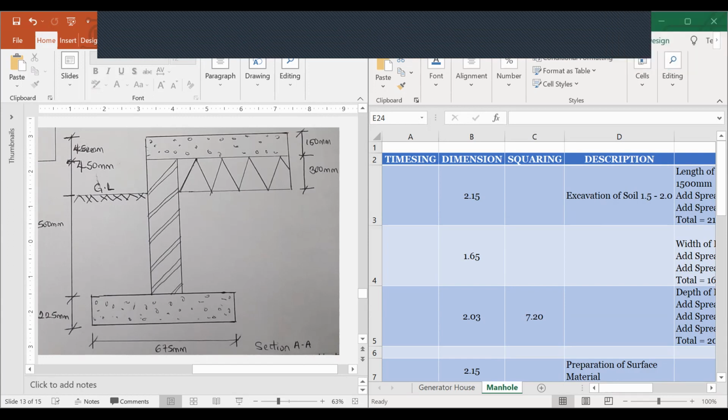Like for the block wall now, we've got 361.24. Is that the total amount of? Yeah, that's the total amount we need for all the units. Okay, the total area of blocks. So basically, how we're supposed to work is, for the area we get, you divide that area by the area of a block. Otherwise you'll not be able to know the number of blocks needed. Do you understand? Thank you very much. Yeah. So let's go to the next one because of time. Time is fast spent.